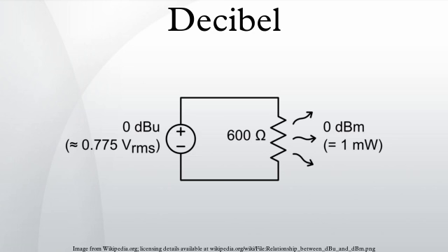Decibel SIL, decibel sound intensity level, relative to 10^-12 watts per meter squared, which is roughly the threshold of human hearing in air. Decibel SWL, decibel sound power level, relative to 10^-12 W. Decibel A, decibel B, and decibel C. These symbols are often used to denote the use of different weighting filters, used to approximate the human ear's response to sound, although the measurement is still in decibel.